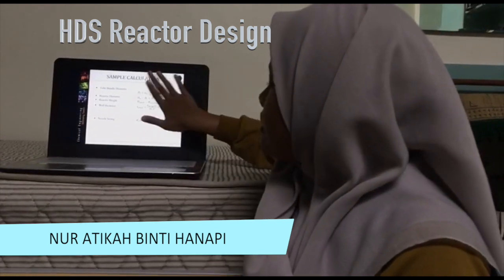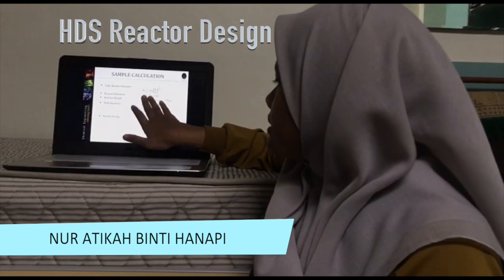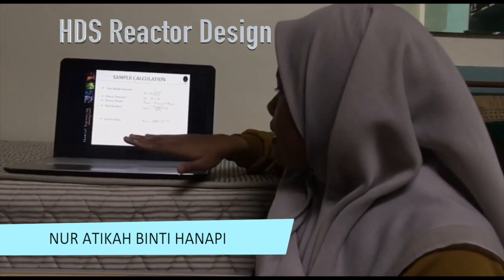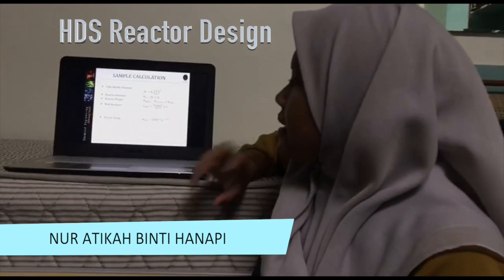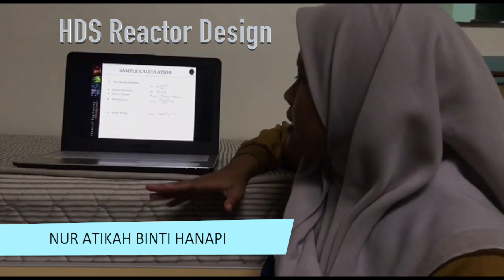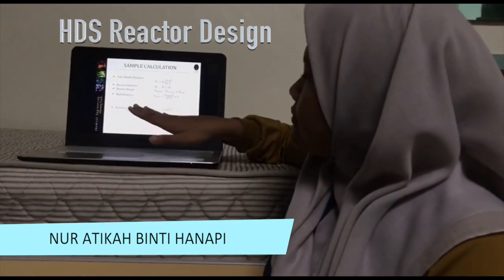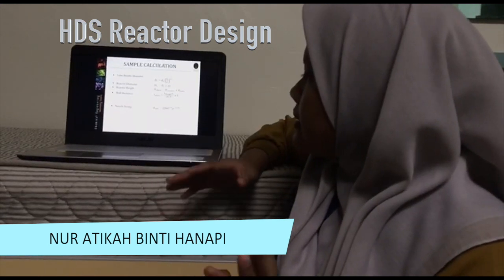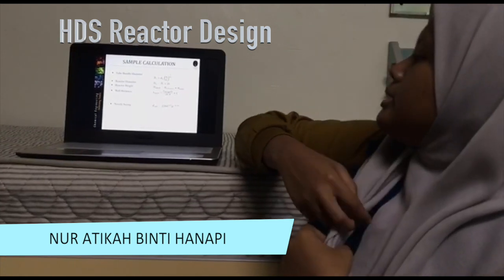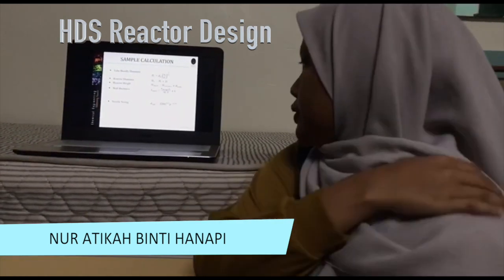This is my sample calculation. This is how I get the bundle diameter. And then for the reactor diameter, I calculate the diameter plus 2 times the thickness. And then for the reactor height, which is the height of the shell, I add the height of closure and height of tube.